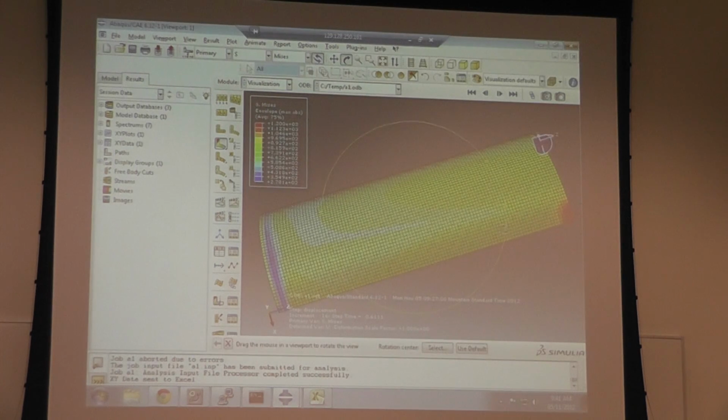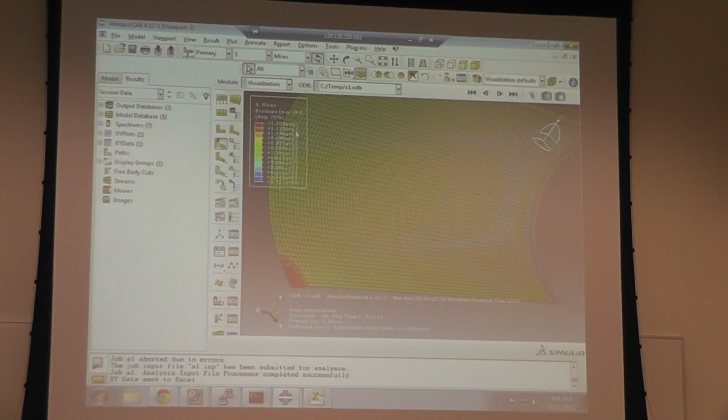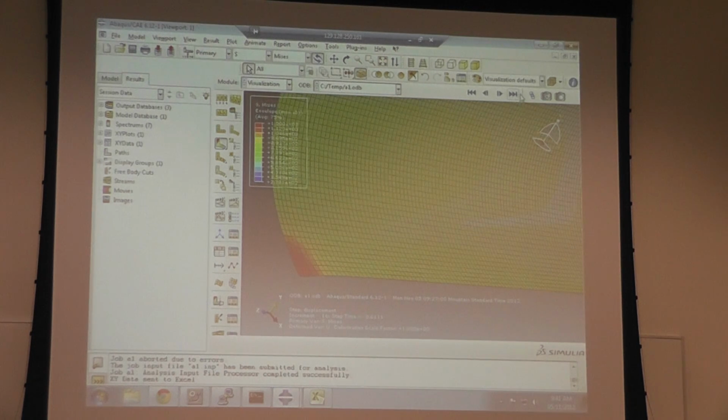and you can see the area where the pipe, where the displacement is, where the contact is applied, and you can see that this area is fully plastified. The von Mises stress reached 1200, which is the maximum stress that this pipe can take. So it has reached the maximum, and as you increase the displacement, what will happen is that this area will get bigger and bigger and bigger without any increase in the stress. Just the area of plastifying will just keep increasing, and so on.